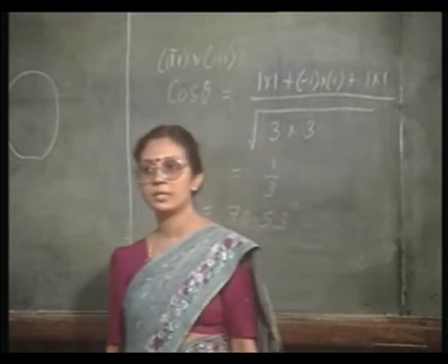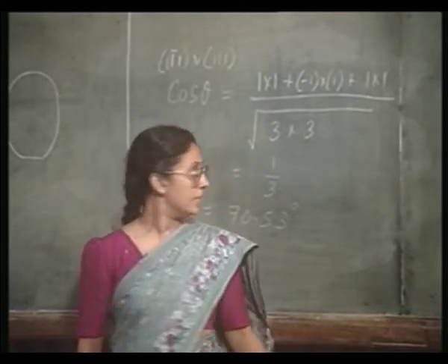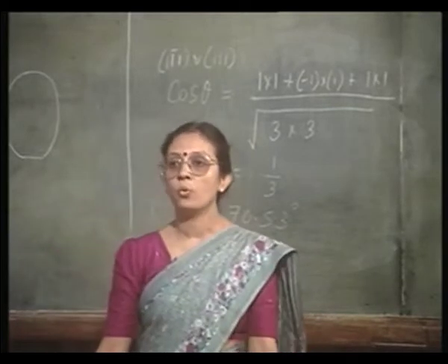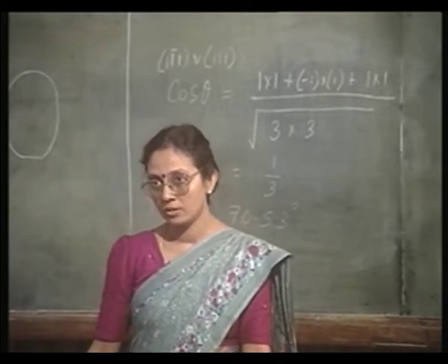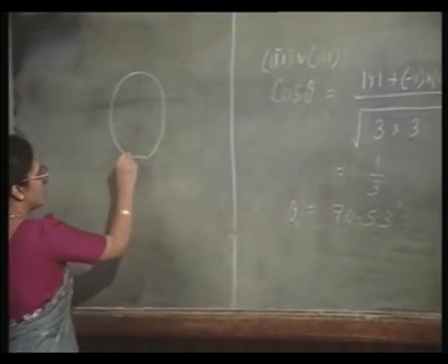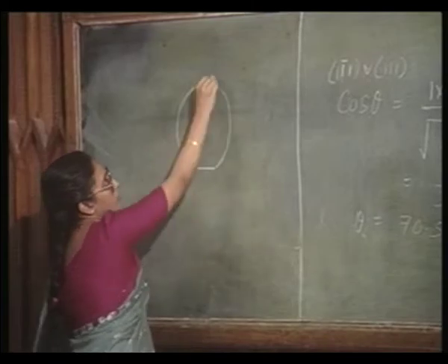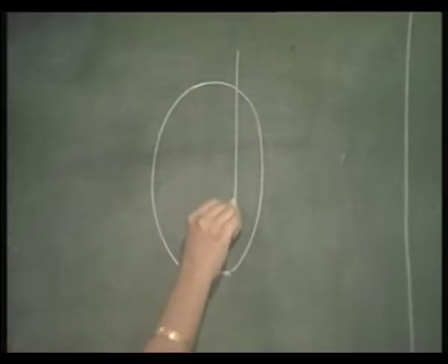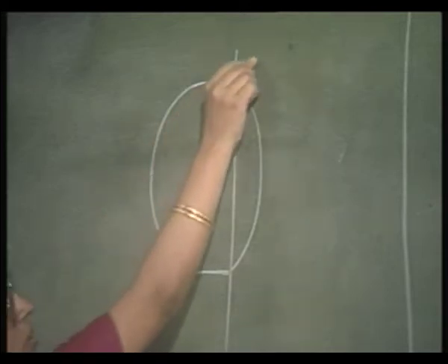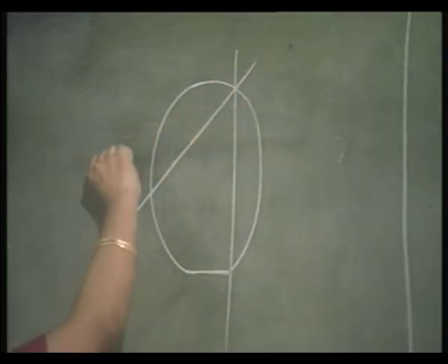But the important point is, even these two planes, they are going to meet in 110 direction. And where are these 110 directions? See, I have provided a flat, therefore, my first scribe line is going to be perpendicular to this flat. Okay. So, this is 110 direction. Where are the other two 110 directions? You know, right?